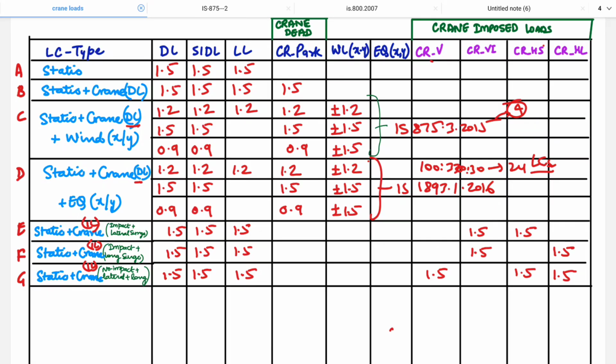There are 4 wheels, no? So you're applying horizontal, vertical and lateral, and combining based on this. So you have to assign load cases properly so that when you're combining in load combinations, they reflect properly. Okay, this is it about today's discussion.